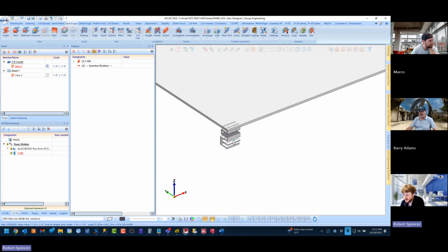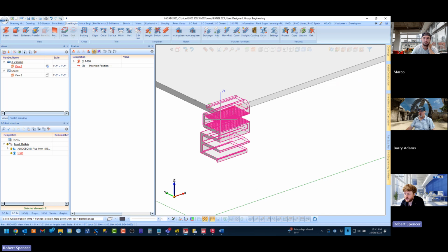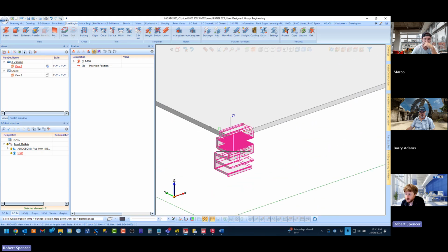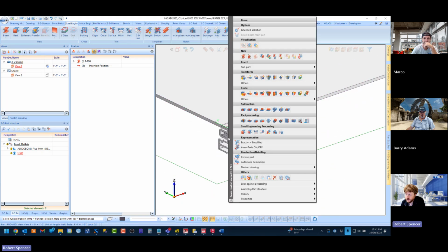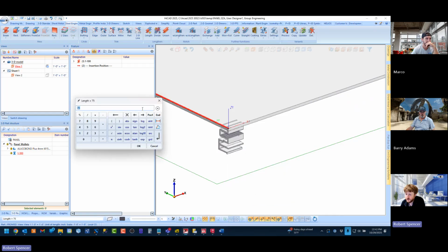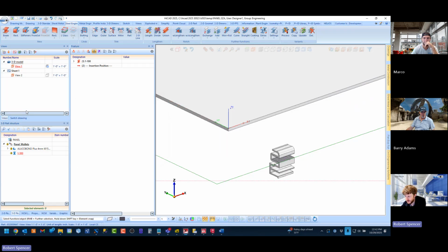Okay. So now all we did was just throw it in here. We just happened to snap to these points. The fact that we clicked these points did absolutely nothing other than just putting it in the drawing. Now here's where I want to give myself a little room to work. So I usually say right click, transform in a direction. Here's where I just click this edge. And because the arrow is going the wrong way, I just give it a negative value and I just kick this out a little bit. I used 4, I don't know, maybe 2 would have been good enough, 3, whatever you want.